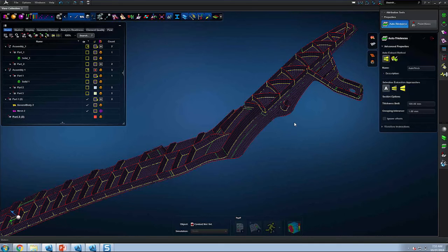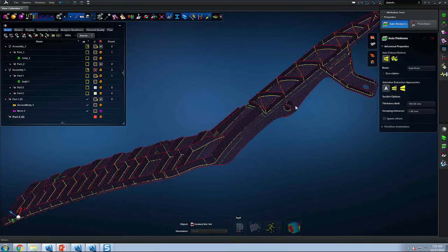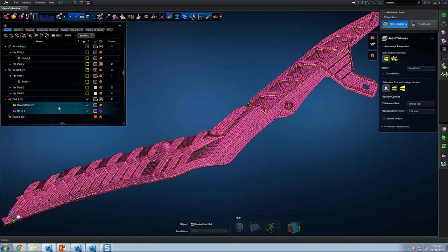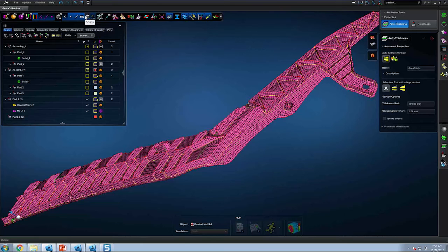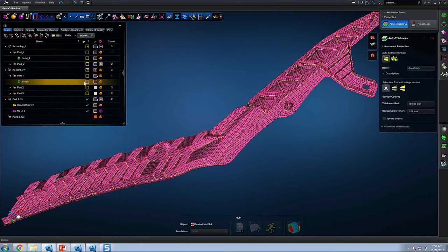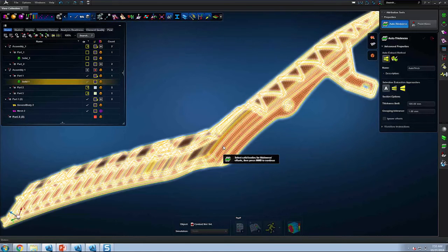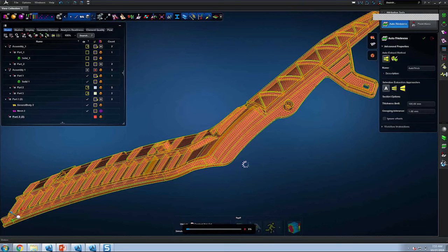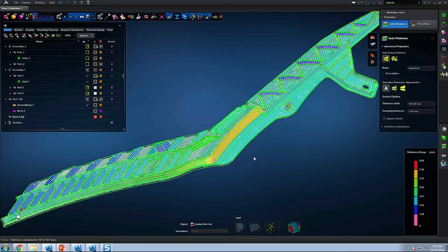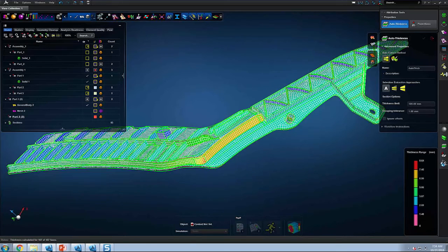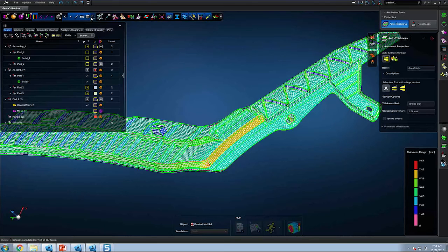Again, there's a lot of drafting in this example. Here, I'll select the initial mesh, and then I'll select its original solid geometry. So the mesh is the target, and the solid geometry will be used as a guide to compute the thickness and offset properties. And you'll see that it's doing it automatically for you. You also have the flexibility of manually editing specific pieces of the thickness. So here we have a color coordinated plot of what the result looks like.